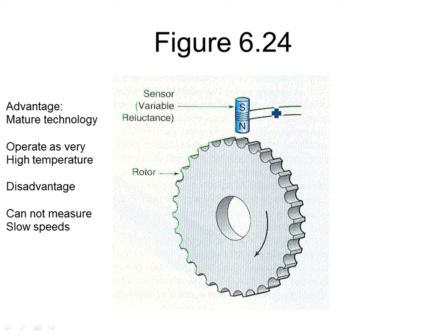We had this over there, but it got thrown away. I think it was a Seco with an SCR drive for a DC motor, and this is what they use to sense the speed on it. They use one of these reluctance pickups. Worked really, really good.